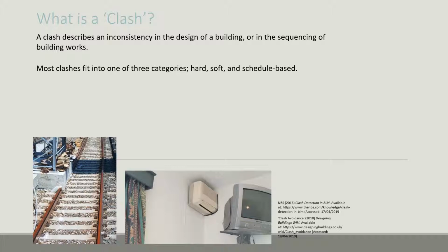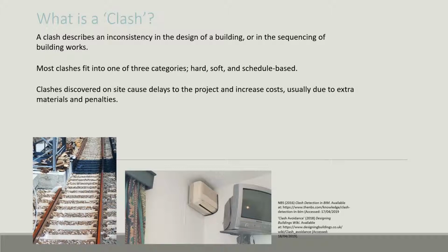Schedule-based clashes are caused by poor, illogical project planning. For example, wagons arriving during the construction of a temporary hard standing, and the hard standing is incomplete so the wagons can't get onto site. Clashes can cost the principal contractor time and money.